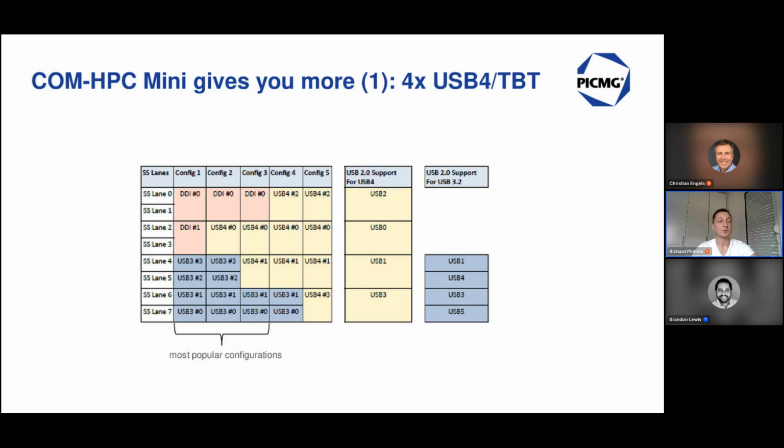Important again, a quick side note from the technical angle. USB4 and Thunderbolt retimers implement DisplayPort auxiliary channel coupling resistors on the retimer ICs themselves, and these parts are placed on the carrier board and not on the module.